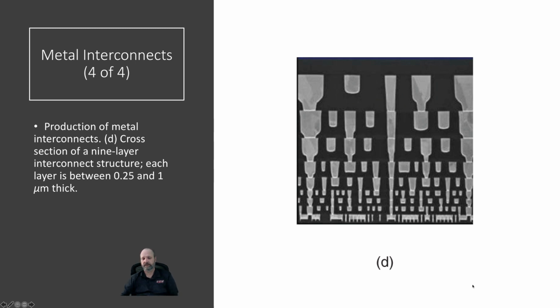And what's really cool to note here, it's the alignment. So if you look at the 9th metal layer and it's aligned to the 8th metal layer, you can see how well aligned it is. It's unfortunate it doesn't have a scale in the X direction, but I would venture to guess it's probably around 1 micron at this left uppermost lead.